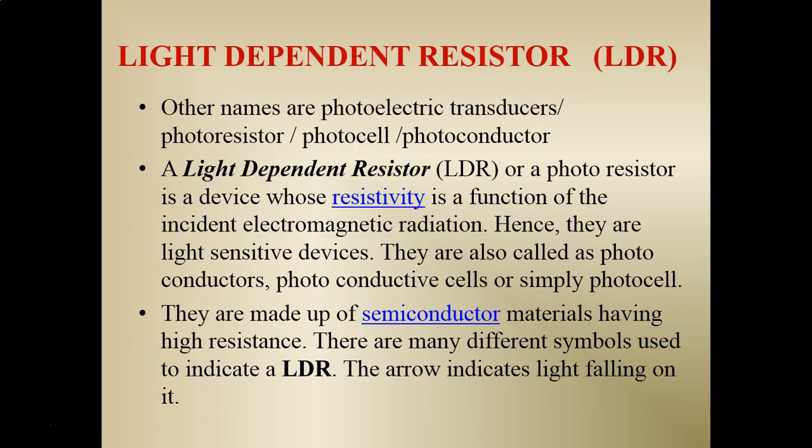LDR, light dependent resistor. Other names are photoelectric transducer, photoresistor, photocell or photoconductor. An LDR, or a photoresistor, is a device whose resistivity is a function of the incident electromagnetic radiation. Hence, they are light sensitive devices.